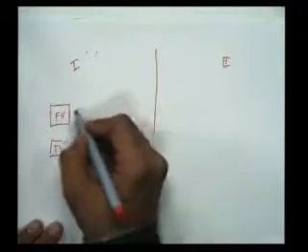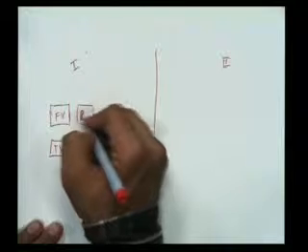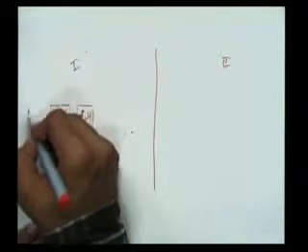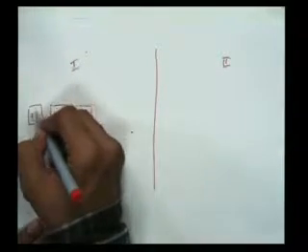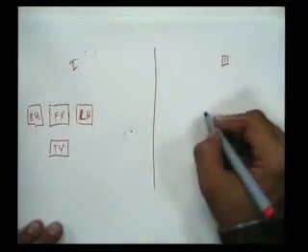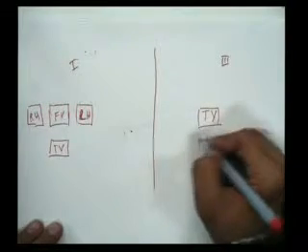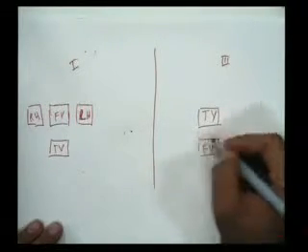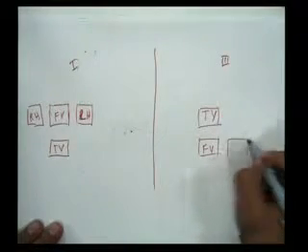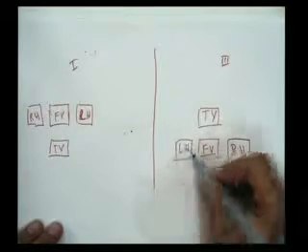On the right hand side I have my left hand side view, and on the left hand side I have my right hand side view. And in the third angle, the top view I have here, below that I have my front view, on the right hand side I have right hand side view, and on the left hand side I have left hand side view.